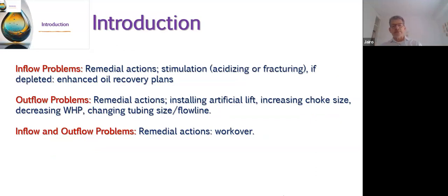Remedial action is needed if the well was initially flowing naturally, but now has reached a point where it is not able to produce the fluid up to the surface. So we need to install an artificial lift, or increase the choke size, or decrease the wellhead pressure, maybe change the tubing size, flow line, etc. For inflow and outflow problems, we need to think of a workover action.